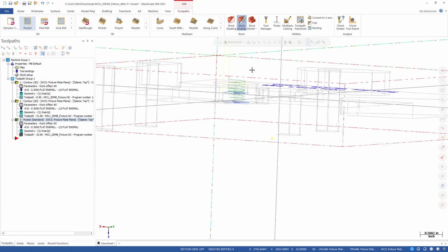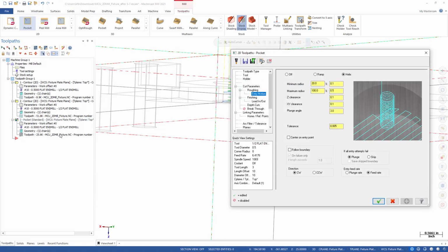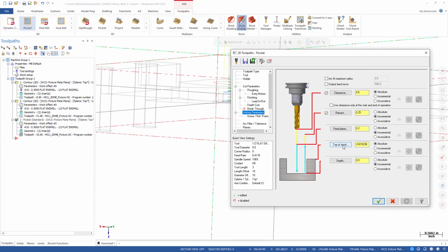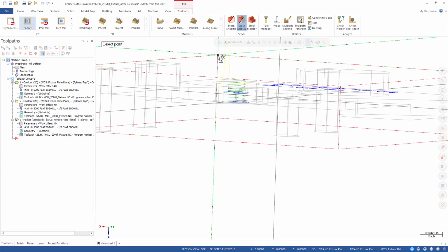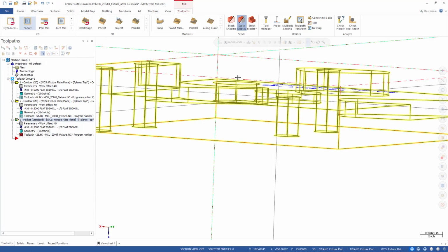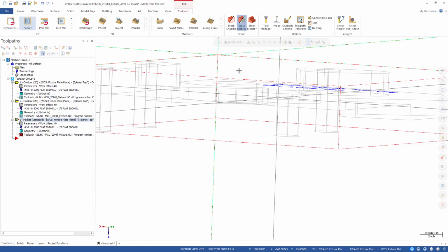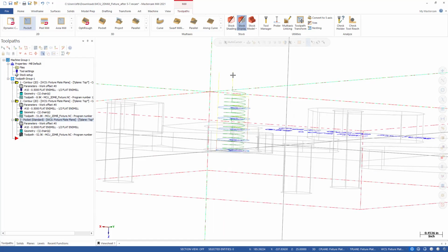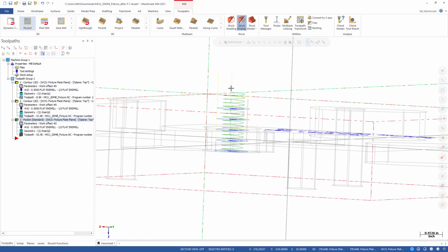So let's do that. Let's go back into the toolpath, and under linking parameters, the top of stock is not reasonable. So let's select it and choose up here to be our top of stock. Now it's back to 0. And if you don't preview the toolpath where it recalculates it, you will get a little red X here indicating that it needs to be recalculated. So you simply select the toolpath and then choose regenerate all selected operations. Now you'll see that this toolpath feeds in from above our material and then starts helicaling through the stock.